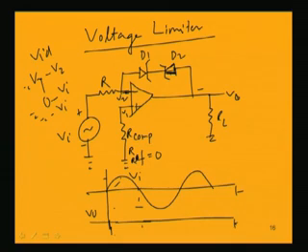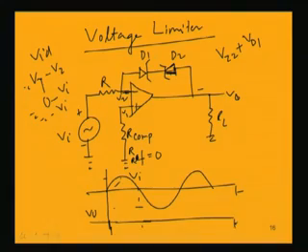That means, we will be getting the total voltage drop V naught as V Z2 plus the drop of D1, V D1, that is the diode drop of D1 plus the Zener voltage drop of the diode D2, because Zener breakdown will be happening, it will be conducting, but in D1 it will be normal conduction, because it is forward biased, and that is happening in the region when this Vi is positive.